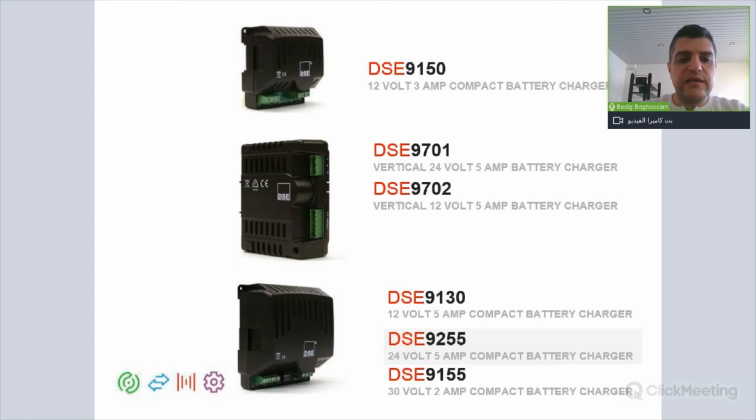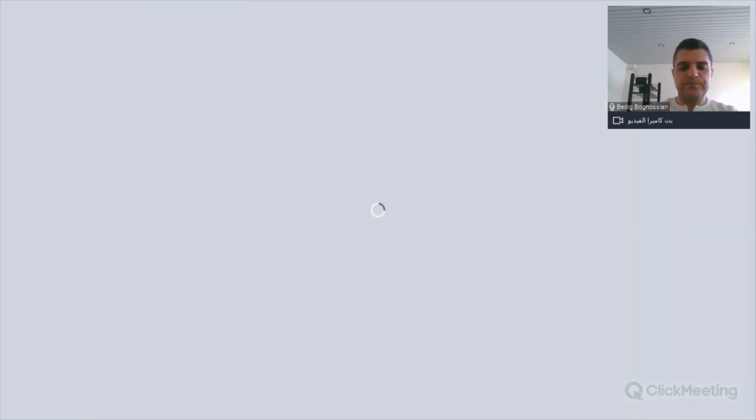And lastly, the temperature compensation and the derate output. All the DSE chargers, even the standard chargers, have temperature sensors on their board. When they detect high temperature, we're speaking about the ambient temperature, when the ambient temperature rises, then the DSE charger will detect that, and it will start reducing its output current, so it protects its own PCB.